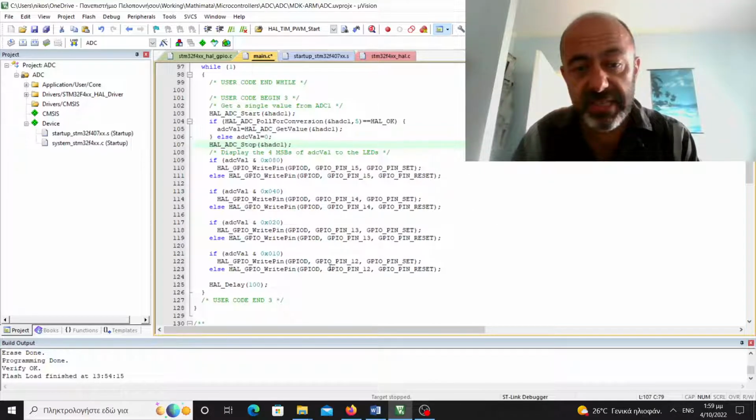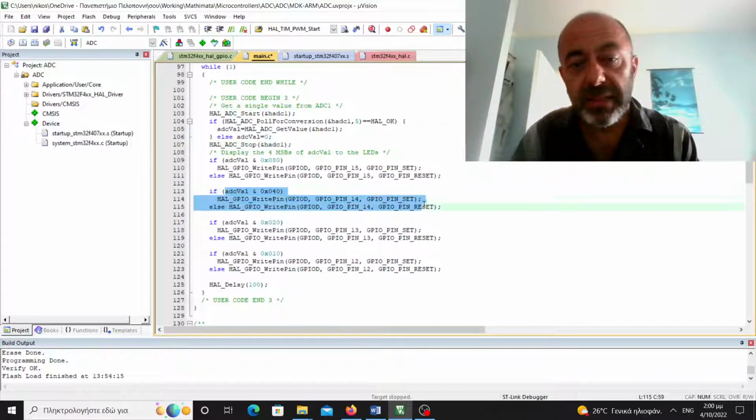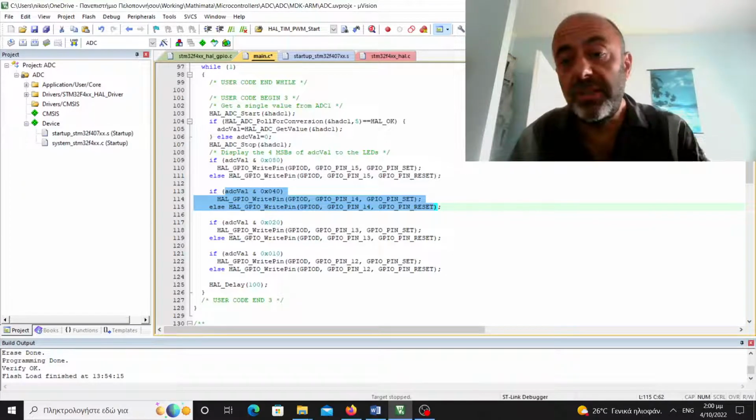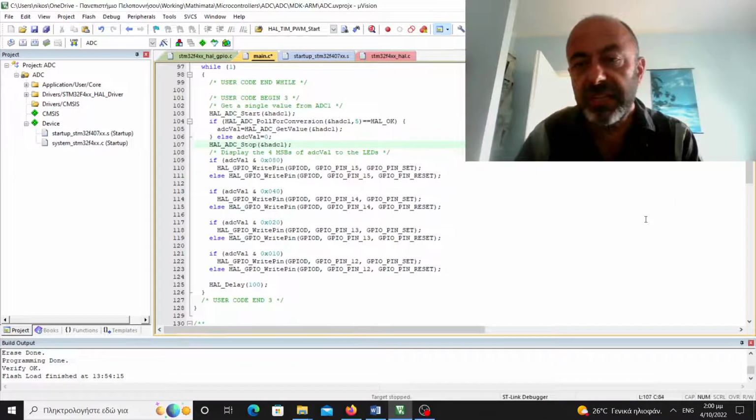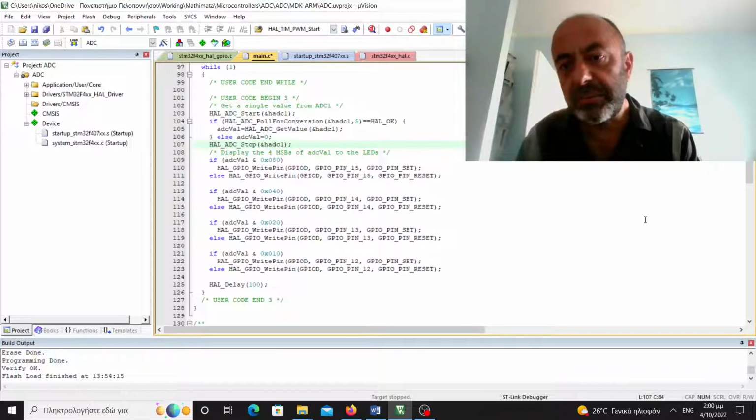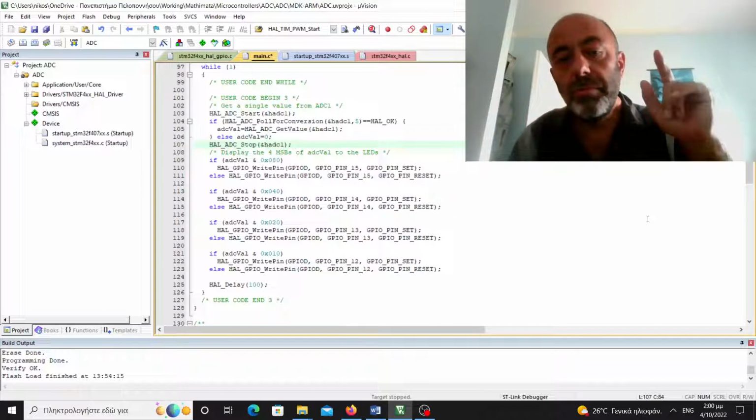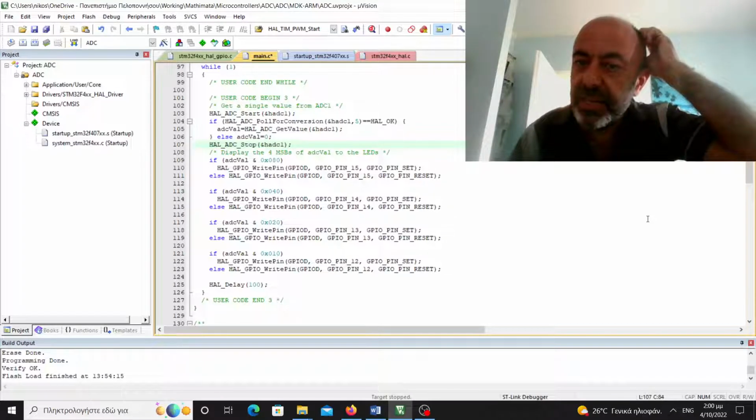This means that this LED will be turned on, number 12, but I also have the bit number 6 at 1, which means that my LED connected at GPIO pin number 14 will also be turned on, regardless of what we have at the rest of the bits. If these values were here, as you see that I changed the least significant bits, no difference would be made. The specific LEDs that I mentioned earlier would be the ones that would have been turned on.